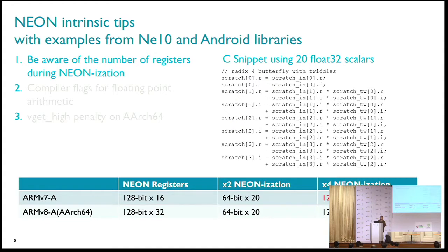To stay compatible between ARMv7 and ARMv8, I always have to consider the limitation of ARMv7 first. So is there a better way of doing that? Can I get hints from the compiler saying that, hey, you're probably using more registers than you should. It'll impact you on ARMv8. Is there a clue to give?